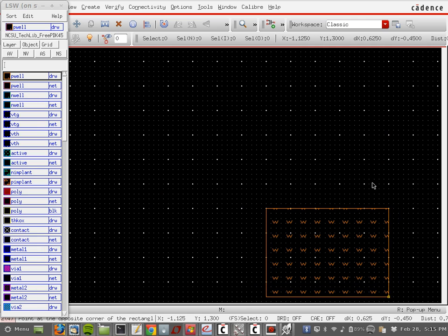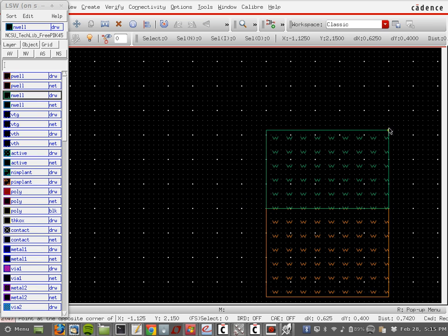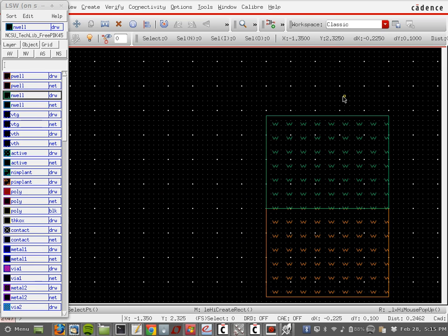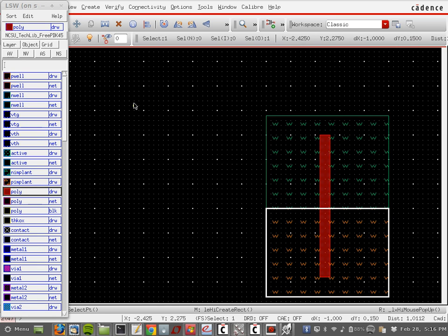I'll make my P-well, and then I make my N-well. Probably needs to be larger than this anyway. And then I make my channel. It doesn't really matter the order which you go in. Like I said, the channel has to be 2 lambdas like this.